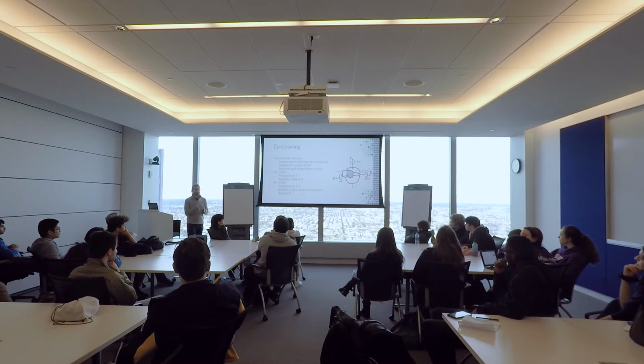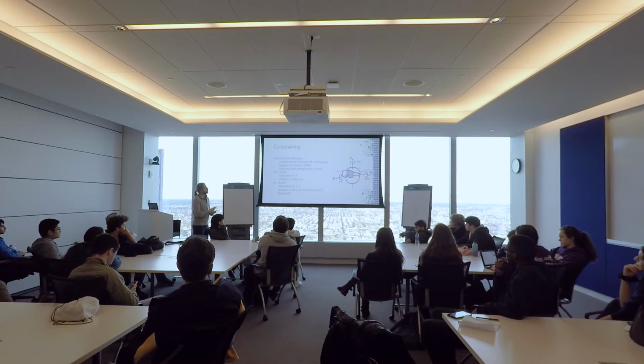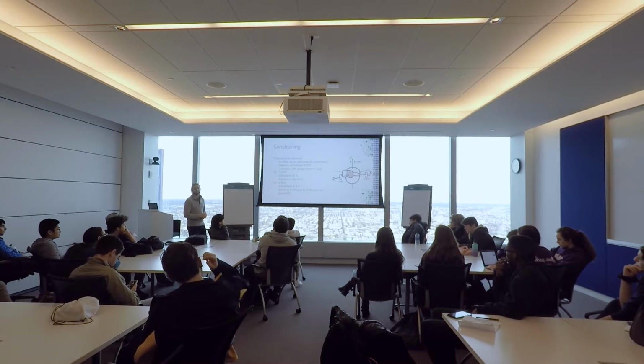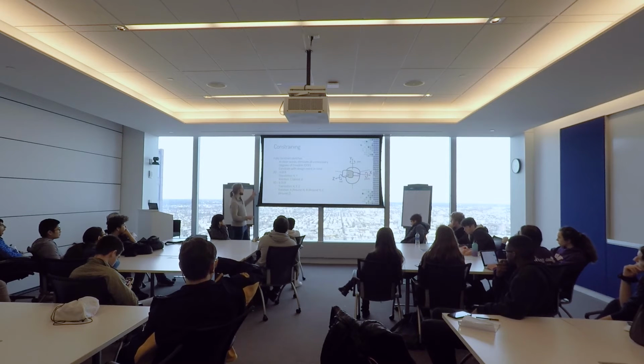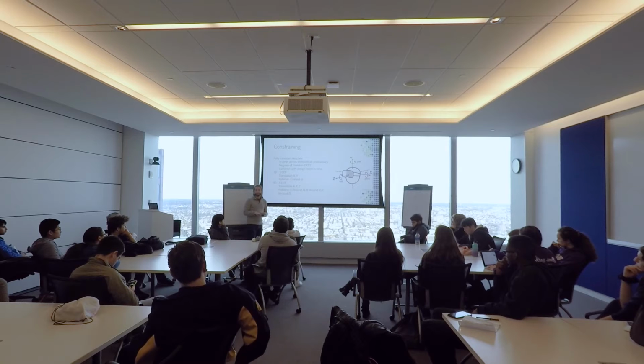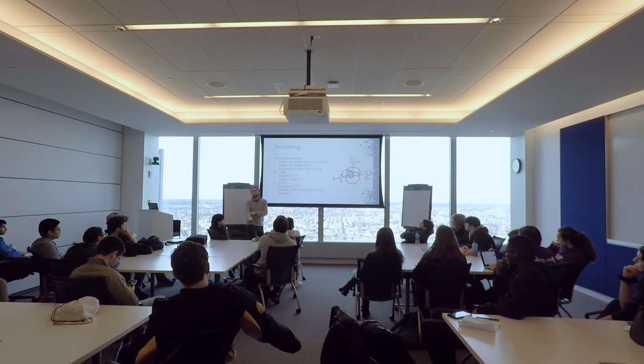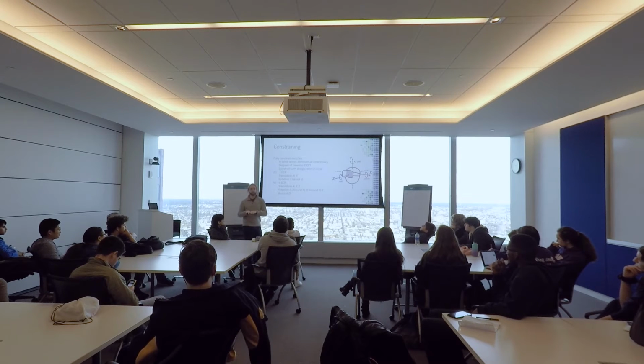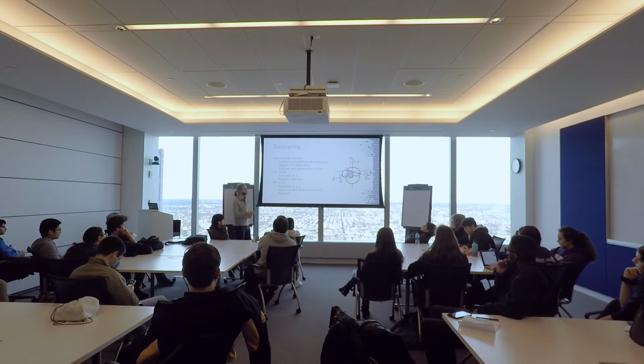All right, constraining in 2D sketches. Generally speaking, when you're modeling, you want sketches fully constrained. There are some exceptions to that, but very few. And constraining is, in 2 degrees of freedom, you have X, Y movement, but also rotate. So that's like a piece of paper on a table can only move in the X direction, the Y direction, and rotate. That can describe any motion of that piece of paper on the table.